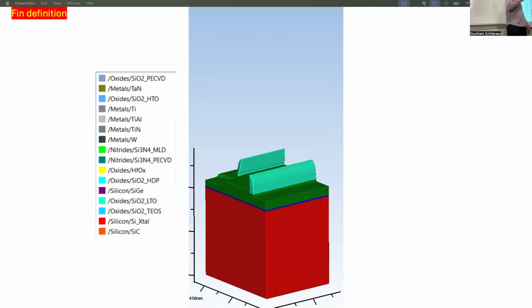How do you remove the polysilicon? This is etching. Don't you etch the oxide? No, because when you etch, what are the things you etch? You etch organics, oxides, nitrides, silicon and polysilicon. You can always select an etch that etches one versus the other. So you can etch poly, but you don't etch oxide or nitride, because there's nitride at the bottom and there's oxide here. If I use a poly etch, it's only going to etch the poly, not anything else around. So that's why the polysilicon is now etched, and you just have this oxide sidewall spacer freestanding.